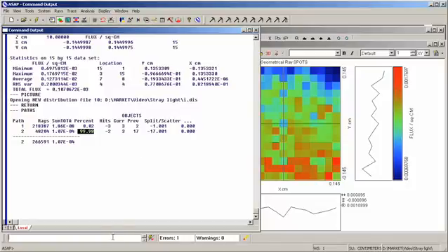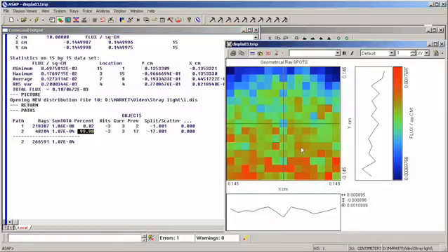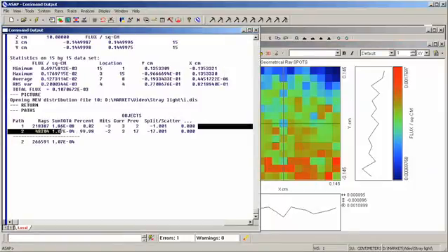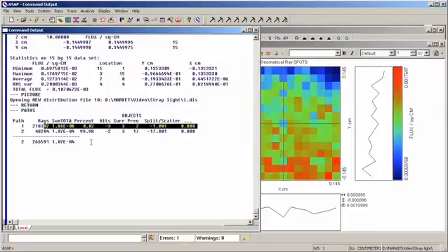Thus we see how ASAP is able to do efficient stray light calculations, do an accurate BRDF fit to realistic BRDF data, and how ASAP shows us not only the total stray light irradiance on the detector, but also ranks the stray light paths by importance and the total power that is on them, so that we can find out those paths that are most important and find out where the problems are so that we can solve them and improve our stray light calculation.